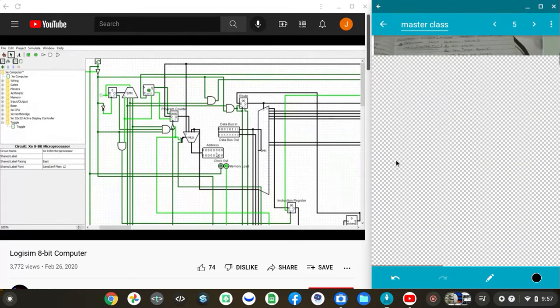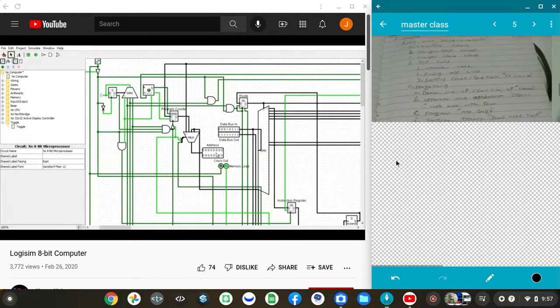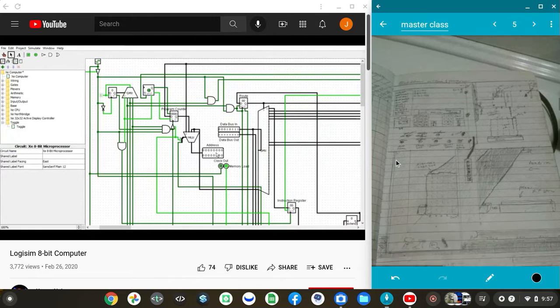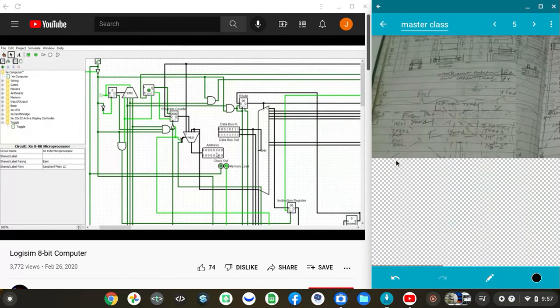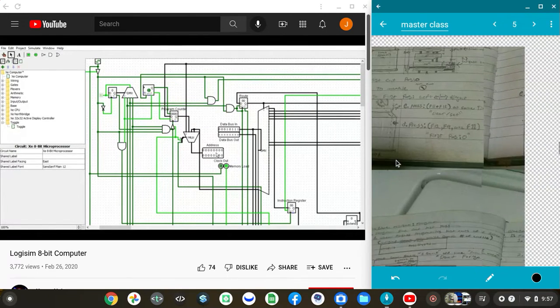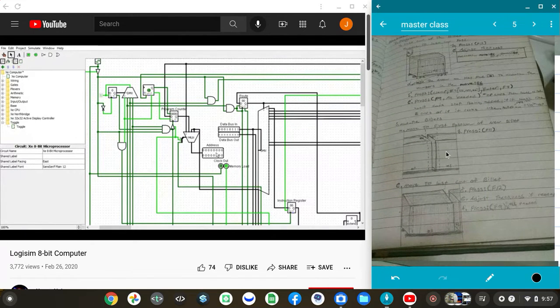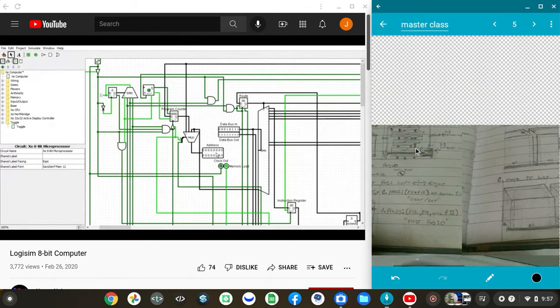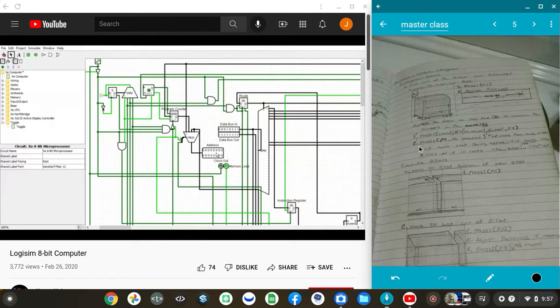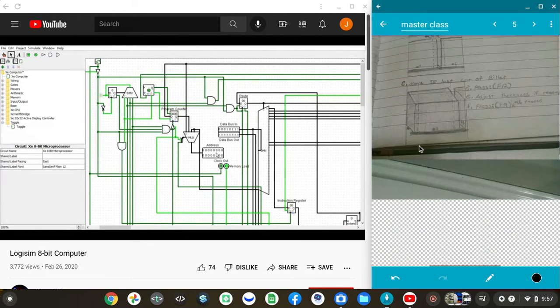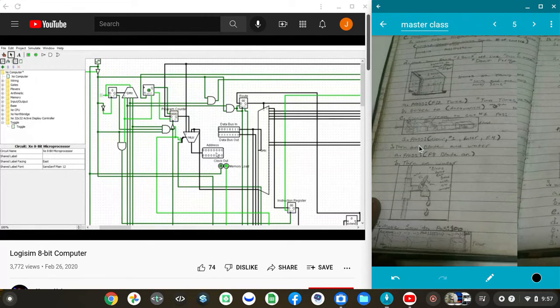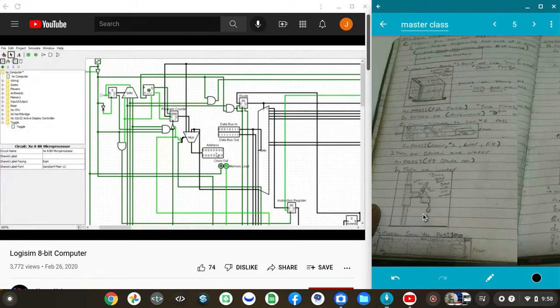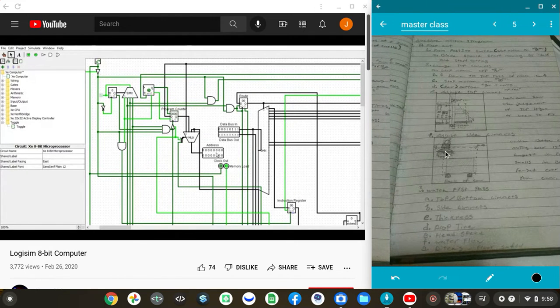Now, the address is an output. And what the address says is where in memory we're currently looking. Whatever we're doing there could be reading or writing, but the address just says that's where we're looking. And since there's a ROM and there's a RAM, there's also a graphics memory, this address can point to one of those three depending on where it is. The very bottom addresses, the ones closer to 0, go to the ROM.